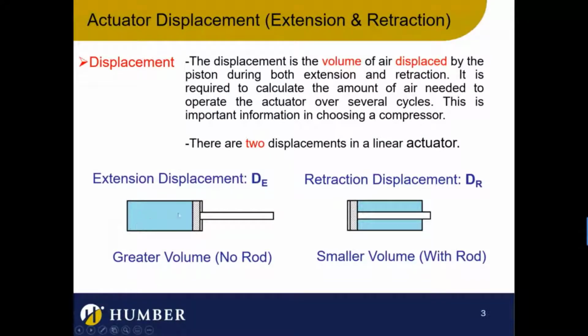That's air that's being put in. Well, the fact is this cylinder then has to retract at some point, and it takes all of this air and displaces it into the atmosphere, and then it's gone. So essentially, we're really calling it displacement, even though it doesn't get displaced till later. But as soon as we put air into a cylinder, it's gone. We've used it, and at some point it will disappear and we'll never use it again. It just goes into the atmosphere.